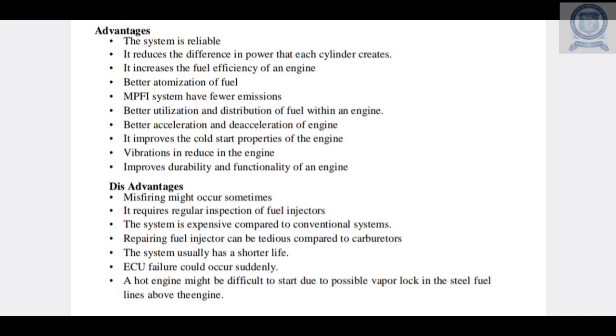Now we are going to list out the advantages and disadvantages of this multi-point fuel injection system. First of all, we can see about the advantages of this system. The first point is the system is reliable, and the second point is it reduces the difference in power that each cylinder creates. It increases the fuel efficiency of an engine, better automation of fuel. MPFI system has fewer emissions, better utilization and distribution of fuel within an engine, better acceleration and deceleration of an engine. It improves the cold start properties of the engine.